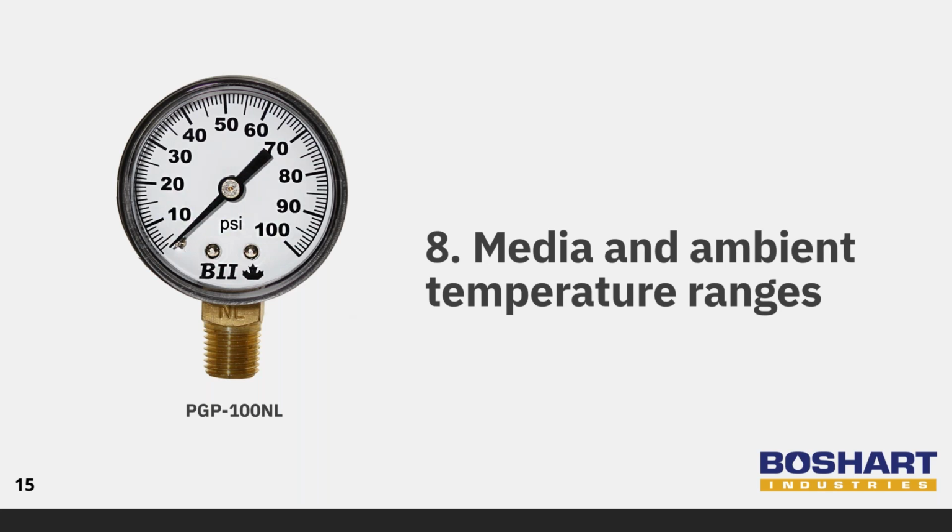Freezing will cause the media to expand, and in turn will cause damage to the gauge as well as possible water damage when the gauge thaws out. Please note that ambient temperatures may affect the accuracy of the gauge. Therefore, the gauge should be isolated from temperature extremes.